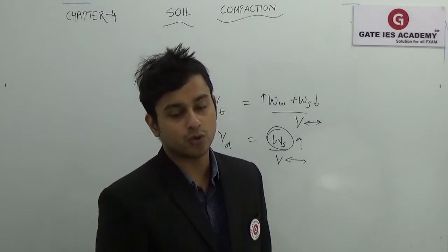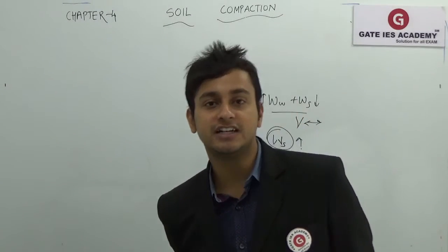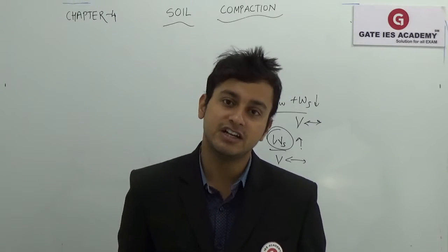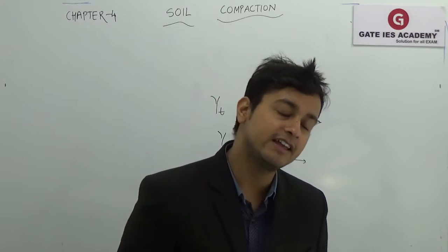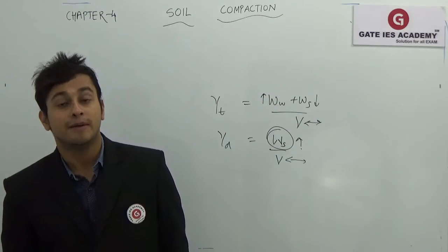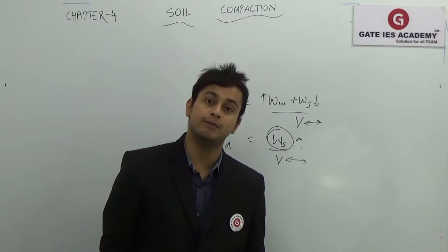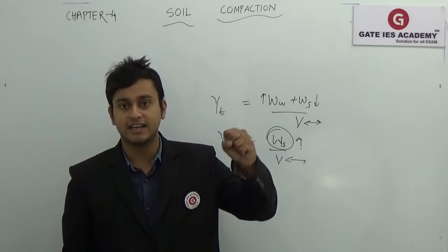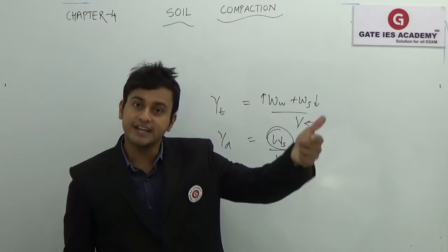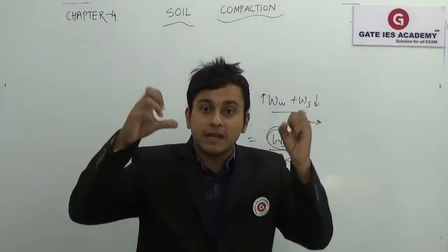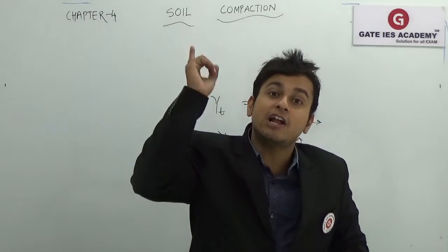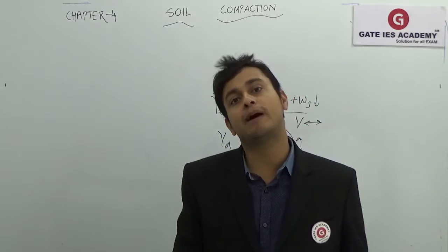Okay, so as you compact the soil, its shear strength will also increase, and later on you will find out that if shear strength is increased, everything gets increased. So its compressibility will be decreased and your bearing capacity, or the load taking capacity, will increase. It will not be compressed now. Voids will be less. How will it be compressed? Its permeability will also decrease. Water also will not pass through the system.